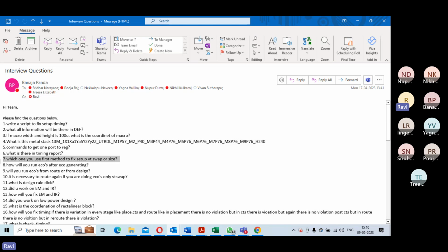So it has to be done manually, and before you do the ECO, you will check that the timing has improved. You source that in the PT session. Make sure in the DMSA session that the timing is all improved.